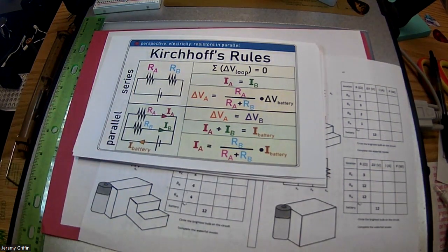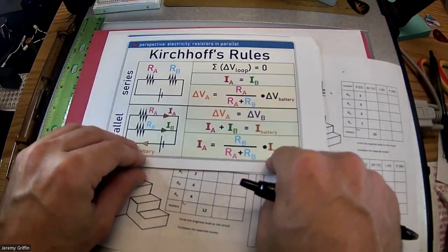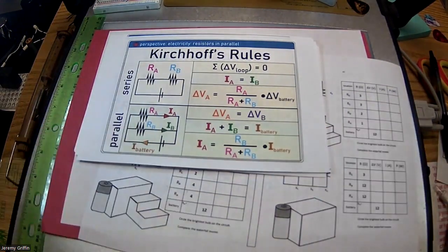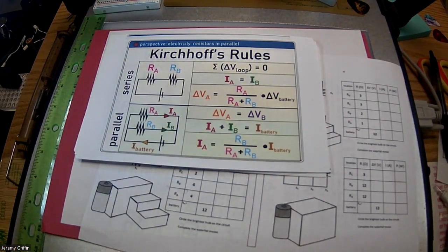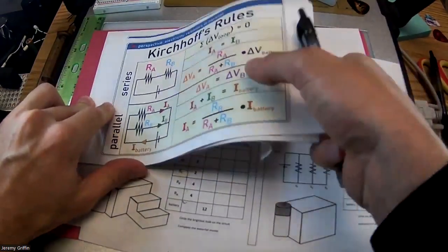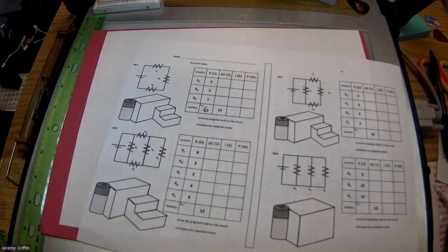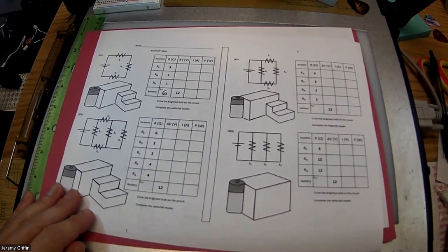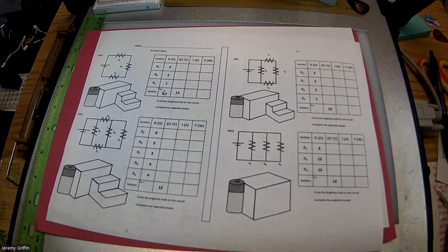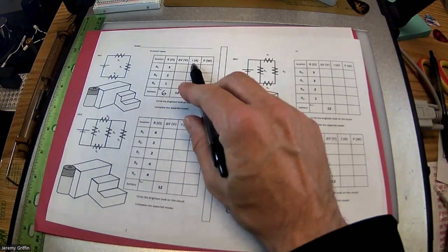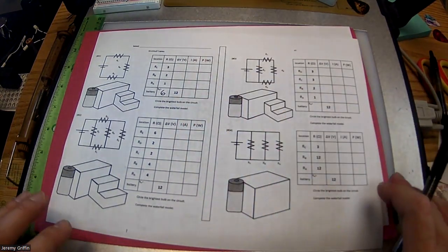So 2/3 of the traffic goes along 1 ohm, 1/3 of the traffic goes along 2 ohms. That makes sense. And then times the original current leaving the battery, maybe like 9 amps or something like that. So with all of that in mind, if you know Kirchhoff's rules, take some practice, take some thinking, we can knock out these Kirchhoff tables. We can figure out exactly what's the voltage drop and the current on each resistor.